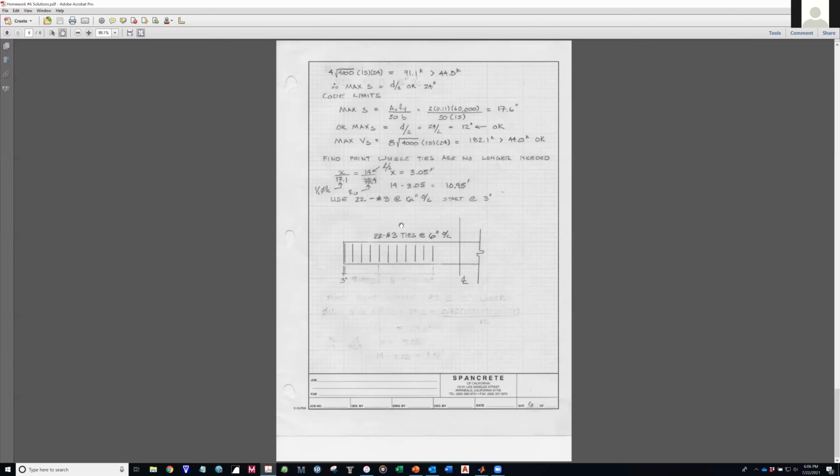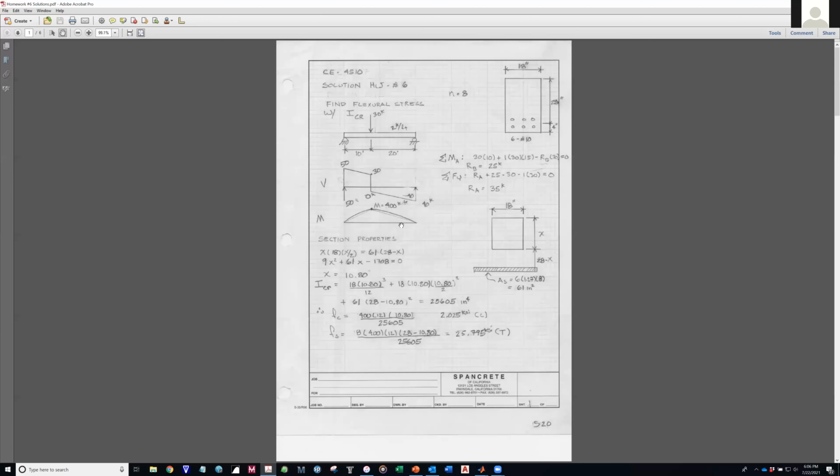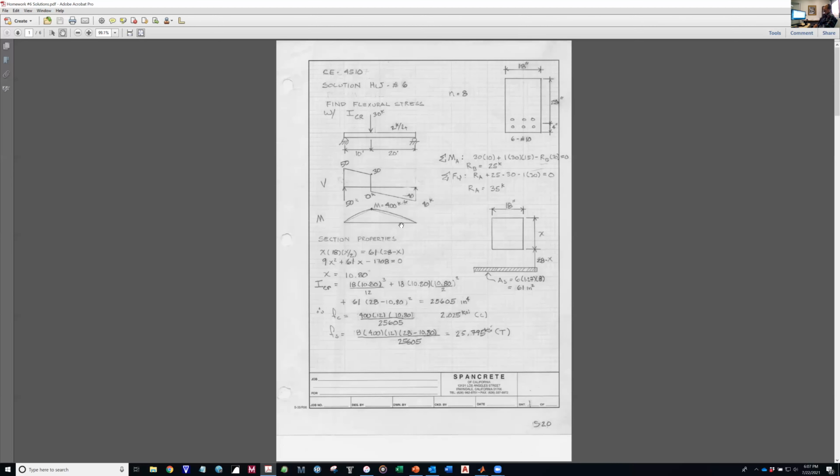And then for number one, I just want to clarify that you do not factor the loads for this one. Correct. We're dealing with the cracked moment of inertia, the cracking moment. What did I ask for? I asked for stress, so those are not factored. That's problem number 2. These are serviceability questions, so correct, you do not factor them.